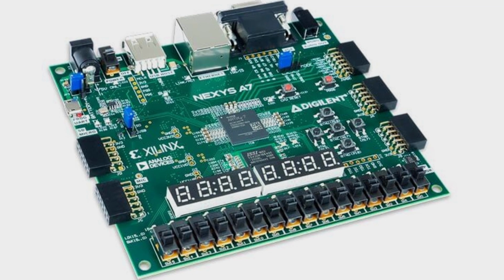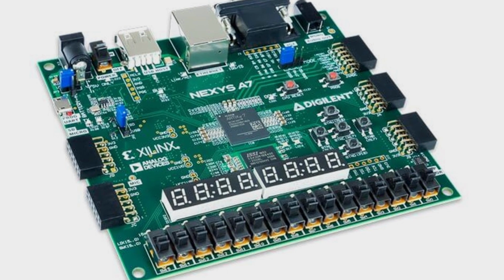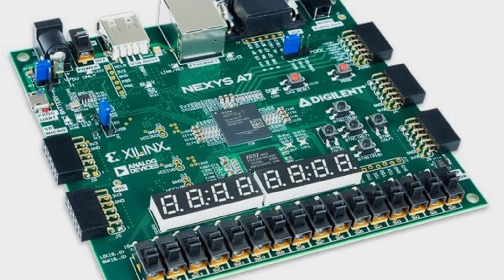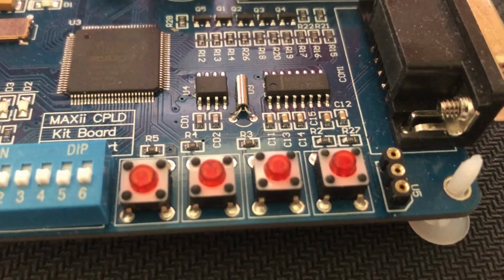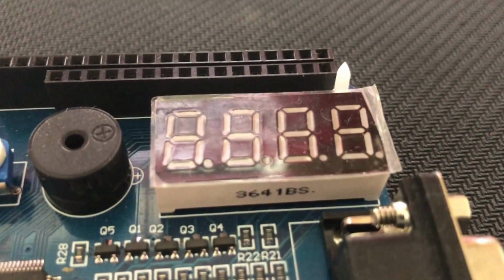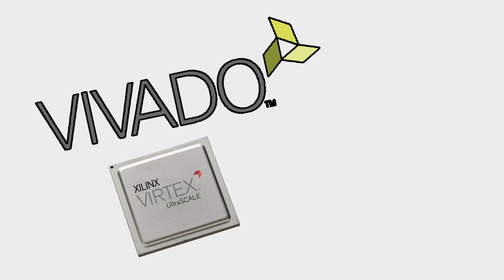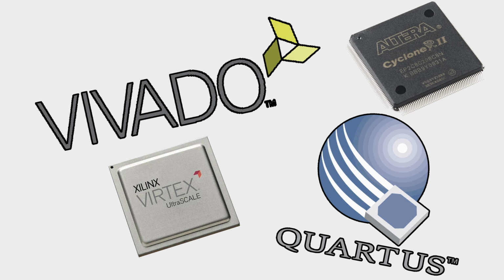Designing an FPGA often requires the use of an FPGA board, which has numerous I/O pins that can be given some form of functionality, whether it be connecting them with buttons, LEDs, buzzers, displays, or other I/O pins. To fully program these devices, proprietary software from the hardware manufacturer is used, usually being Xilinx ISE or Vivado Design Suite for AMD's Xilinx FPGAs, or Quartus for Intel's Altera FPGAs.